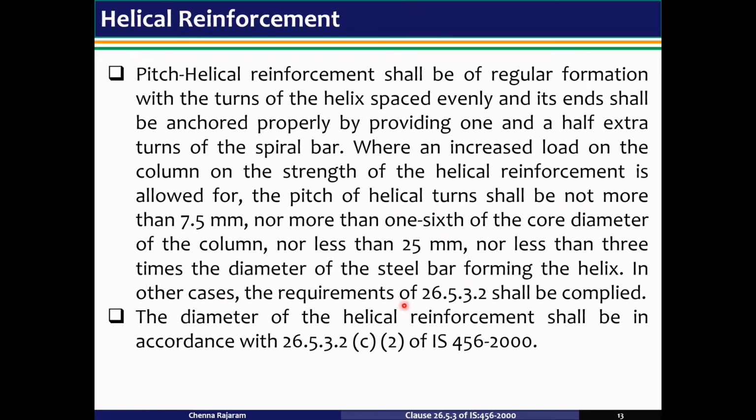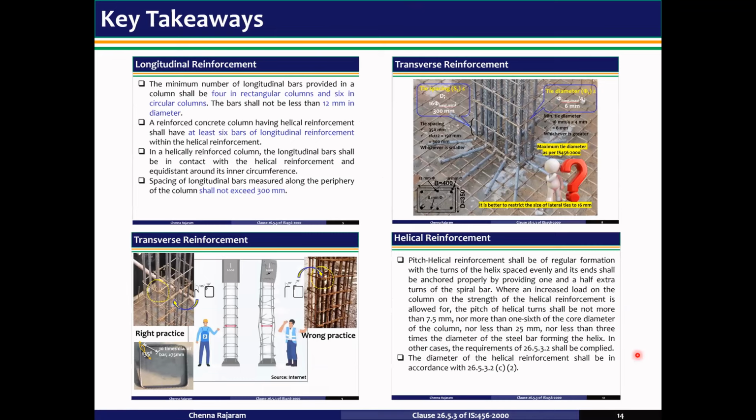In other cases, the requirements of 26.5.3.2 of IS 456 shall be complied with. The diameter of the helical reinforcement shall be in accordance with 26.5.3.2 C2 of IS 456-2000.